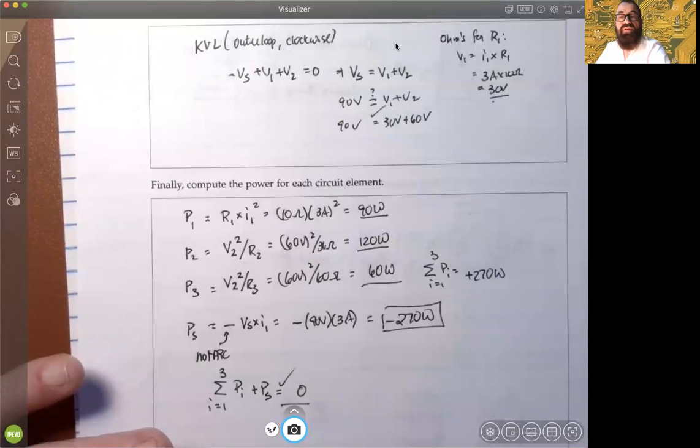If you have an equivalent resistance in series with another one, you know the current through that equivalent is the same through the other resistance it's in series with. So you just have to maintain your understanding of what is shared, whether it be current in the case of series or voltage in the case of parallelism.